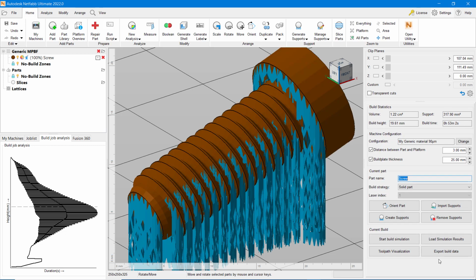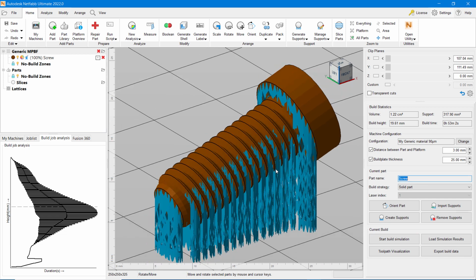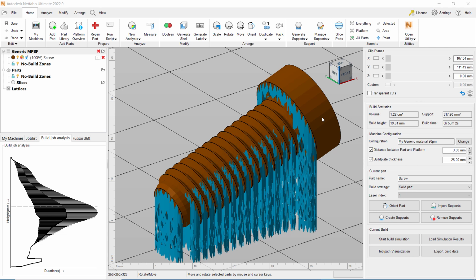The EBPA configuration provided toolpath parameters and it also calculated the toolpaths. An EBPA can also contain its own exporter to write the toolpaths into a file, which is then used to build the parts on an additive machine. Netfabb does not know the meaning of these EBPA parameters, nor does it know how to create toolpaths based on these parameters or how an EBPA-based file format looks like, because all this is managed by the EBPA. So an EBPA encapsulates much of the know-how which is required to run a certain additive machine.